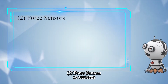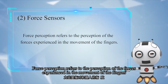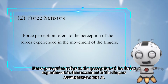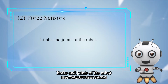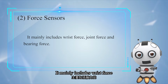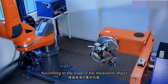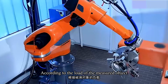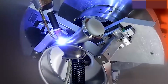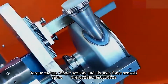Second, force sensors. Force perception refers to the perception of forces experienced in the movement of fingers, limbs, and joints of the robot. It mainly includes wrist force, joint force, and bearing force according to the load of the measured object. Force sensors can be divided into load sensors, torque meters, finger sensors, and 6-axis force sensors.